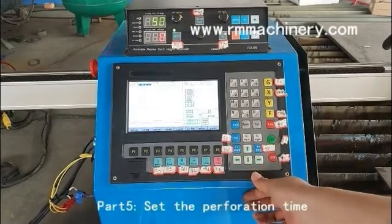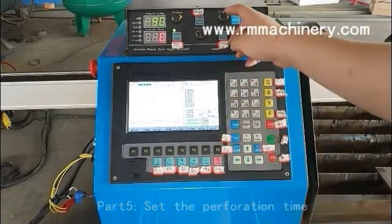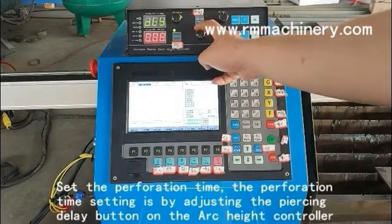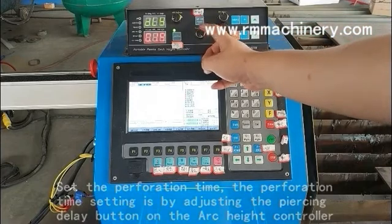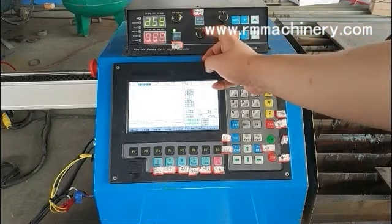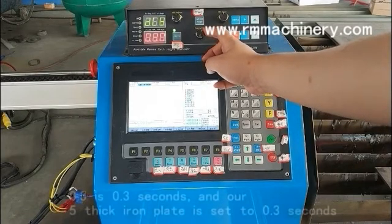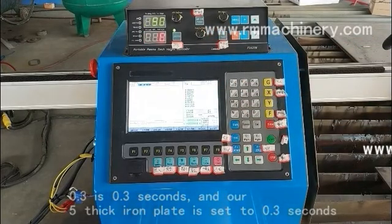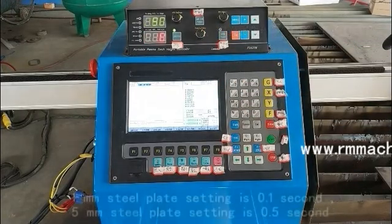Set the perforation time. The perforation time is set by adjusting the piercing delay button on the arc height controller. .3 is 0.3 seconds, and our 5 mm thick iron plate is set to 0.3 seconds.